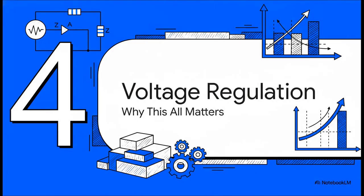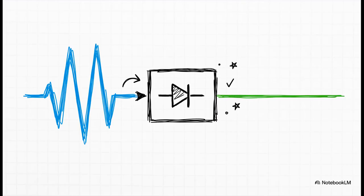So we've looked at the construction, the physics, the graphs, but let's circle all the way back to the beginning. Why does any of this actually matter? How does this little component solve that big power problem we started with? It all comes down to its number one job, voltage regulation. The whole purpose of a Zener diode in a circuit is to take a messy, fluctuating voltage and create a perfectly stable, constant output voltage. If you remember one thing, remember that.